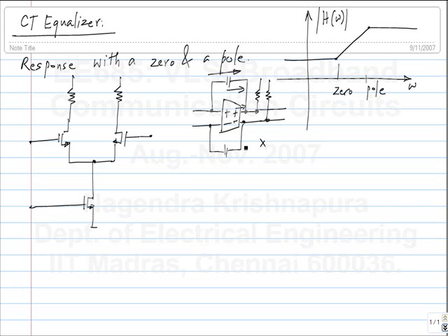Feedback path, okay, that's a possibility. Essentially, that is what this is, but you don't want it this way. Let's consider feed-forward amplifiers. So, if you want a response that is rising with frequency, you have to use an inductor or a capacitor. You can't just have resistive circuits. That is very clear, right?